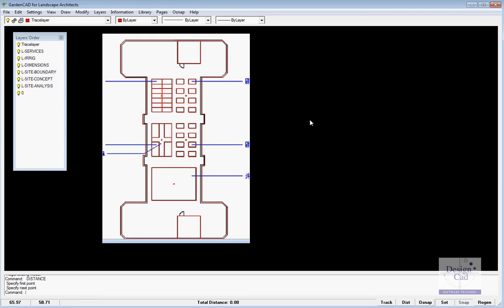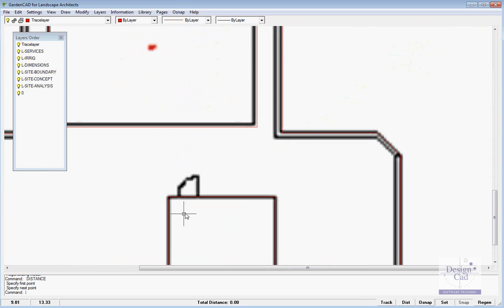The next thing we need to consider, of course, is size, and our client has not given us any information at all about the scale of this scanned drawing. We'll make a guess by zooming in on a doorway. Now, most doorways are of the order of 720, 760, maybe 800 mil, but 760 in Australia is a standard size for a doorway.